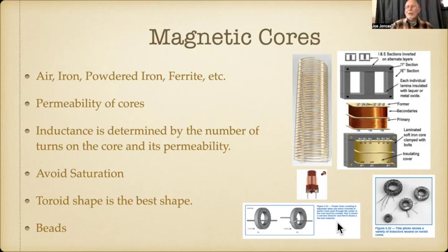You can also use toroids. You just take these things here and you get 6 or 7 of them and you slide them over the top of the coax as it hooks up to the antenna, and it keeps RF from going back down the coax. Now, speaking about permeability, these come in all kinds of material, and they have different kinds. Scott, do you remember, it seems to me like there's a number 31 and a number 62 core material. Do you remember what those are?